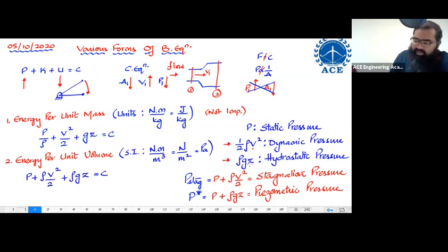Again, when I'm taking this Z over here to define hydrostatic pressure, which Z should I write? Imagine this Z is Z1 and this Z is Z2 over here. Z1 is equal to 4 meters, Z2 is equal to 0. Which Z will I write? Again, I will write the initial Z, which was there, which later on became 0. So that means I'm supposed to write Z1 over here. I hope you are following all these things. Very good.